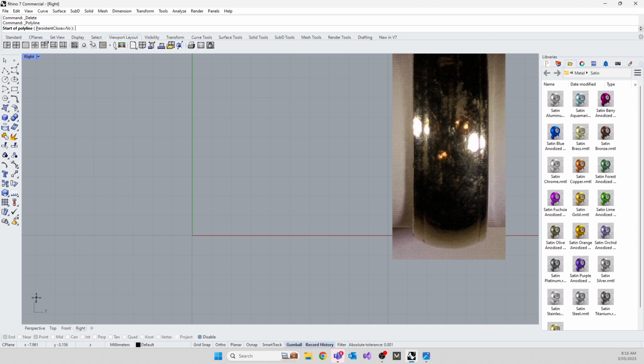There's your axis Z, and there's your axis Y in this viewport. There's 1 millimeter up in Z, 2 millimeters up in Z, 3 millimeters up in Z. Here's 1 millimeter over in Y, minus 1 millimeter over in Y. So if you want to draw from the exact center of the world, the shortcut in Rhino is just press 0, and it assumes 0 for all axes. And you press enter. So now we're drawing from the center of the world.